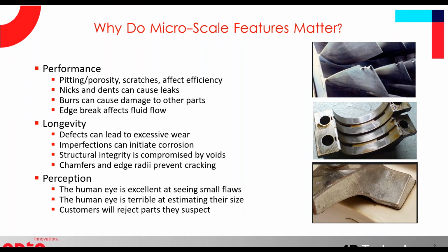Microscale defects have a significant effect on components. They'll, of course, affect performance in terms of pitting, porosity, scratches, all can affect efficiency. Nicks and dents can cause leaks in critical sealing surfaces. Burrs can, of course, cause damage to other parts. Edge break can affect fluid flow.